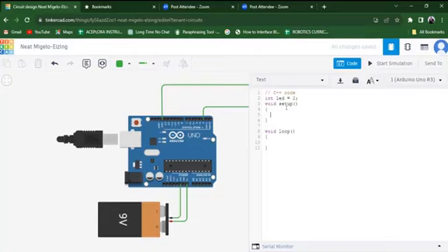In this case, we want the LED to turn on or turn off, and that will happen when the Arduino sends a signal to the LED. So when that happens, the LED comes on, and that function becomes an output function, because the Arduino is giving out data. It is only input when the Arduino is receiving data, but since the Arduino is sending out data, it becomes an output function. And the function we use in declaring that is called pinMode.